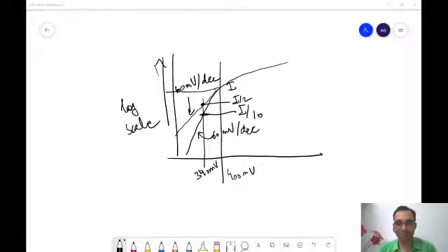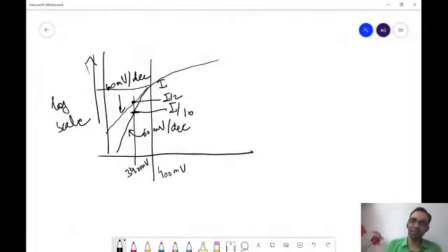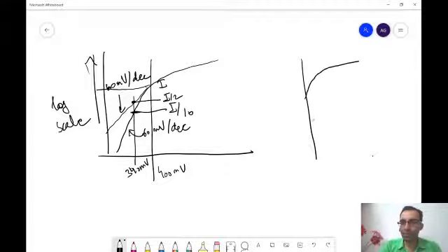When the inversion layer is formed, then we say that. Okay, so Gagandeep says, in the last class we discussed that when the band bending happens such that it is equal to 2 phi, that is when we say VT is there.